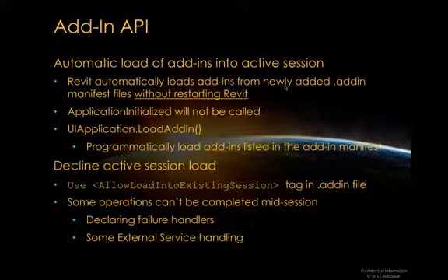Another new API is the add-in API, which enables for the first time the loading of an add-in into Revit in mid-session. So you can load a new add-in manifest file without restarting Revit. Obviously, in this case, the OnStartup method of an external application will not be called. So an application that is willing to participate in this process needs to deal with that situation. There's a load add-in method to programmatically load an add-in.